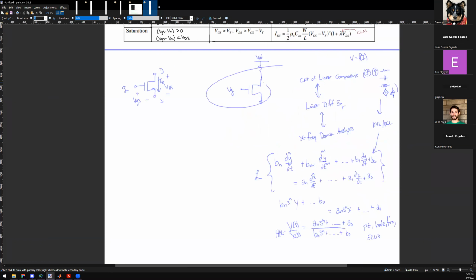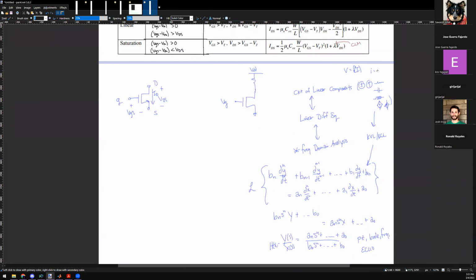And the problem is that this thing is not going to be linear. This thing cannot generate this type of circuit. And you can see linear means that even differentiation counts. So that's why capacitors are considered linear, because I equals C dV/dt. As long as I have a current-voltage relationship that follows this form, even the differentiations of it, it's still linear. An inductor, V equals L dI/dt, is still linear because the inductance and the capacitance are constants. V equals IR is linear because V and I are related by a constant R, and so on and so forth.